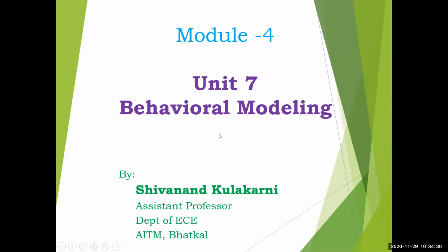So behavioral modeling. In the previous two units, we have seen different types of Verilog programs. First we started off with gate level modeling, and then we took up the data flow level description. In your logic design, first the I/O diagram is there, then you write the truth table, and from the truth table you write the K-map and get the simplified Boolean expression, and from that you write the logic diagram. This is the design part.